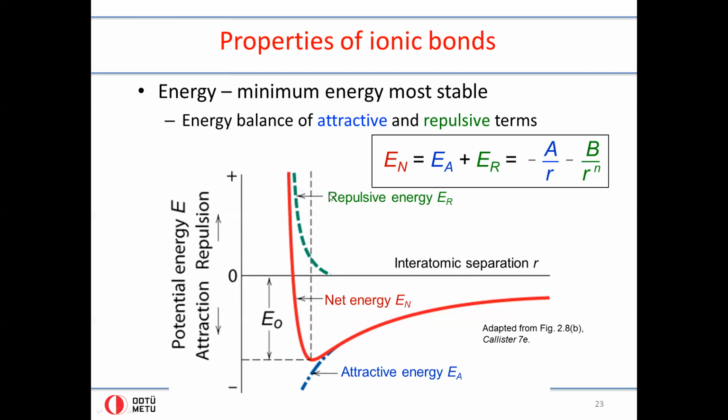And you might imagine that this zone is unhappy because the atoms are too close to each other. Hence, they are net repulsing each other, pushing each other away. The other zone is not stable or happy because the net energy is attractive. Hence, they're pulling together. And this point, and only this point, is the distance of the two centers of the ions where both are happy.